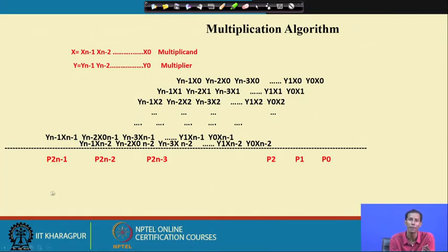That will be the 8th bit. So whenever we multiply n bits with n bits, it will be n plus n, which is 2n. Suppose I have x of m bits and y of n bits. At that time what will be the product length? m plus n.